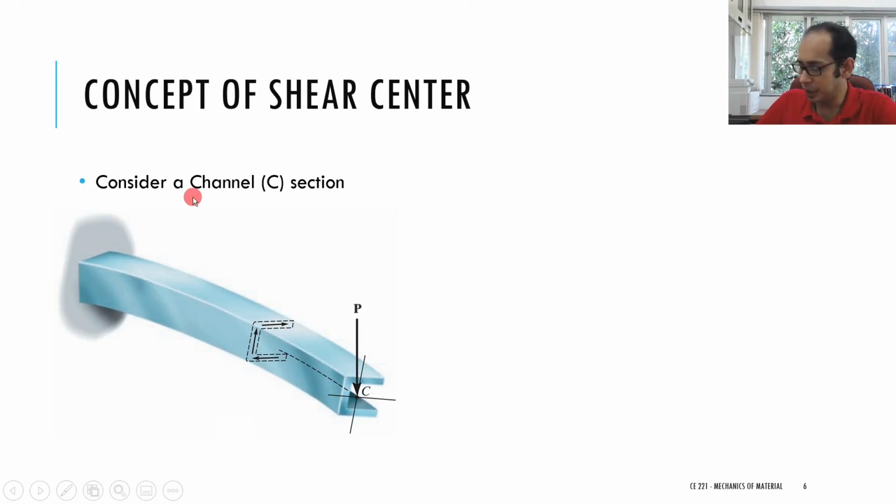This is essentially like if you are taking a beam. Let me turn on my pen so that I can show you. Suppose you are taking a cantilever beam for that matter, and you're applying a load P. If you take a section somewhere and only take the right hand half, what you essentially see is that you have this load P, and you will have this V and the moment and so on. I'm not drawing the moment. This is the V equals P that you are having, which is essentially this vertically acting load over here. So you're looking at an internal section over here.